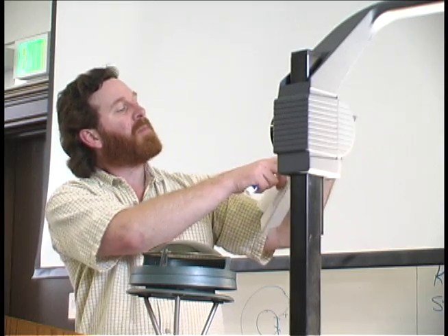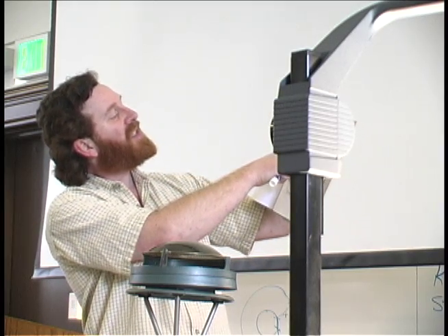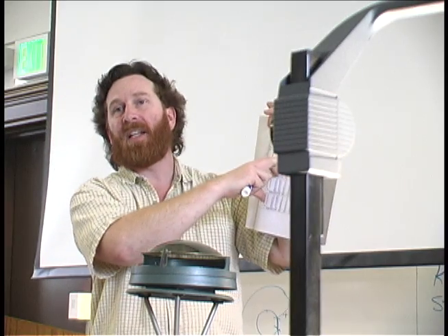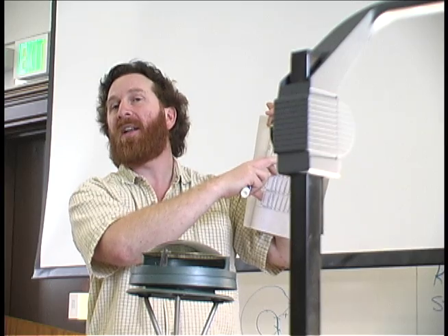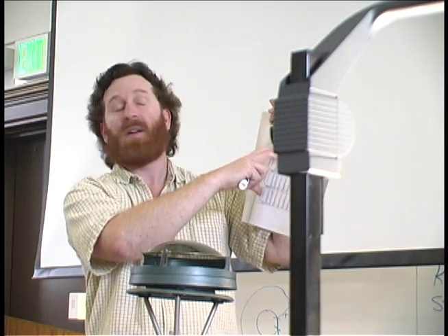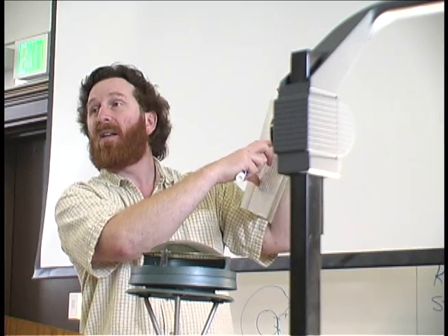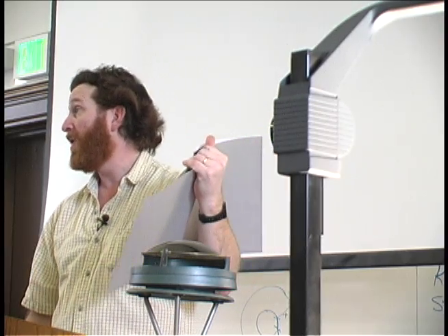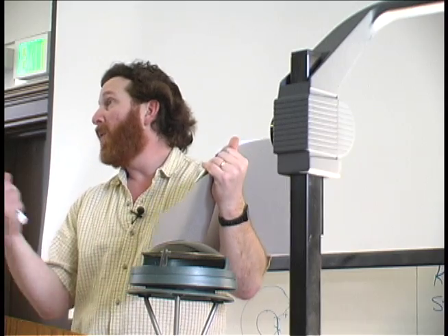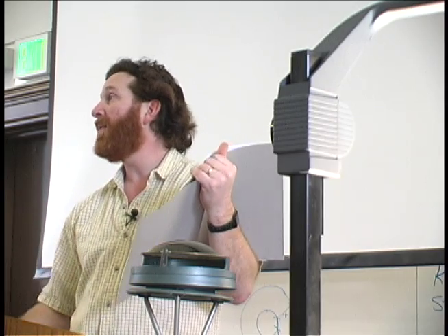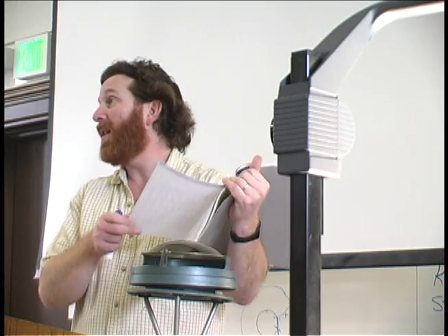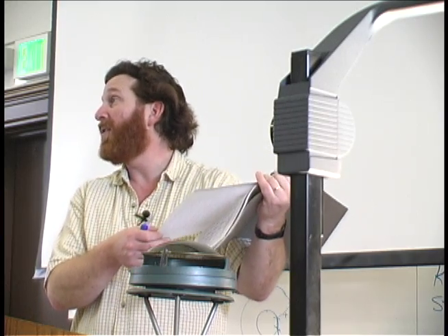So yeah, solar position, ALT is altitude, AZM is azimuth. Horizontal is how much energy in BTUs per square foot is hitting a horizontal surface during these hours of the day and these months of the year. So you can actually figure out how many BTUs you're getting. And then if you figure one pane of glass is letting 85% through, 2 panes of glass is letting more like 75% through, you can actually calculate how much heat you're getting into your house.